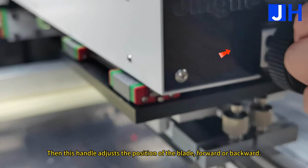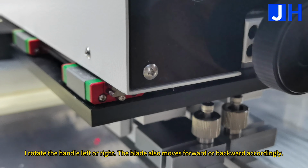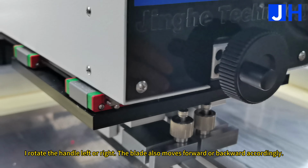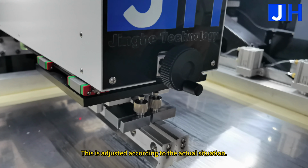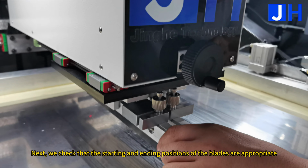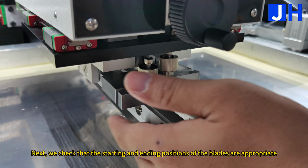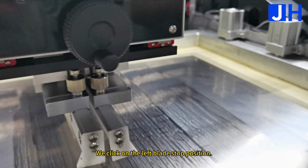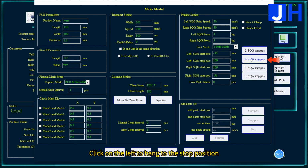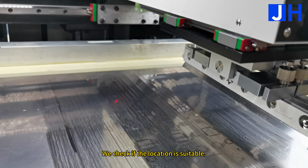Then this handle adjusts the position of the blade, forward or backward. I rotate the handle left or right. The blade also moves forward or backward accordingly. This is adjusted according to the actual situation. Next, we check that the starting and ending positions of the blades are appropriate. We click on the left blade stop position. Click on the left to go to the stop position. We check if the location is suitable.